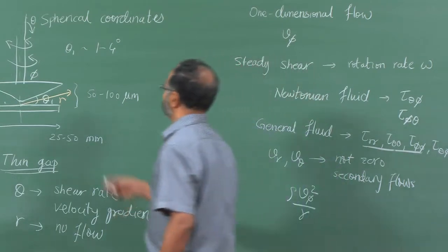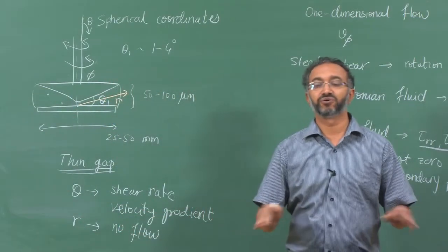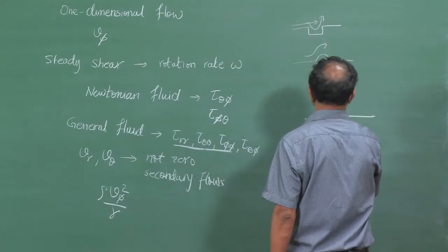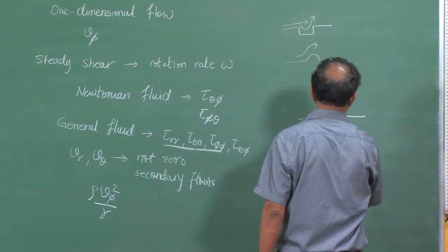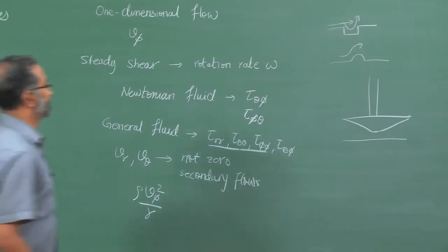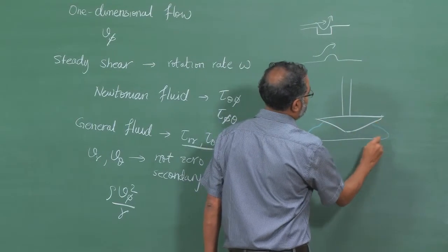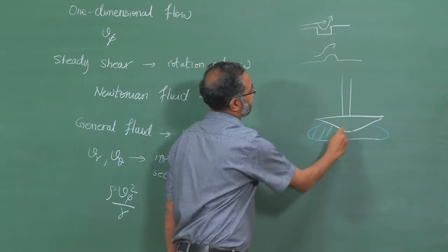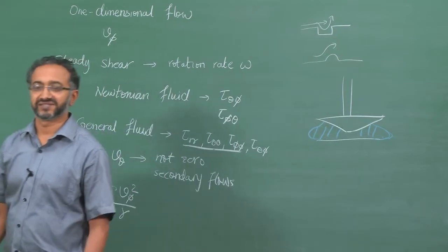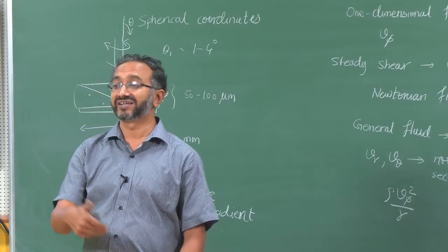So, if you have a material here, and secondary flows lead to some of the fluid going out, so that after some time you are in fact doing experiments with only a limited material, if this is the fluid, it has gone out and it is no longer contacting the overall surface. So, in that case it is certainly possible that you might measure viscosity lower than the correct value.